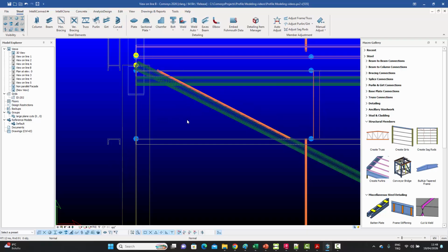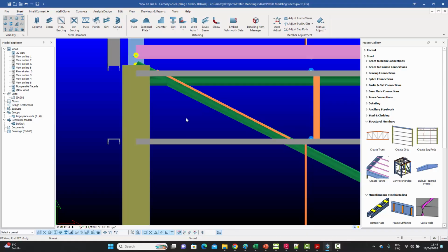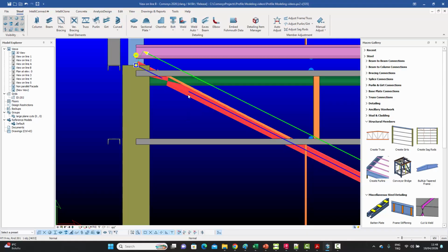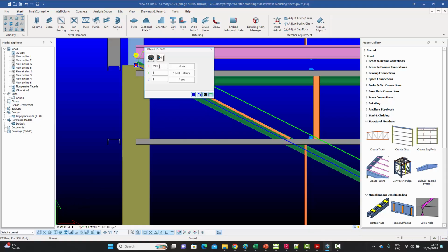So we select this, put it in a better draw mode if you want. You can select this. We can select this blob over here. And since it's the Y direction, we go over here, say -150, move.